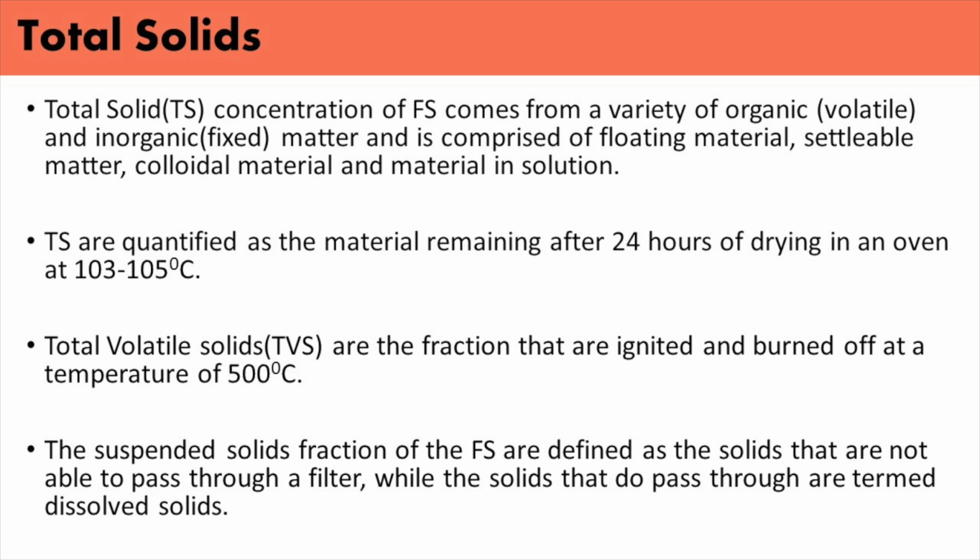The total volatile solids are the fraction that is ignited and burnt off at a temperature of 500 degrees Celsius. This fraction is also considered to be the organic portion. The fixed solids are the amount remaining after ignition and are generally considered to be the inorganic portion.